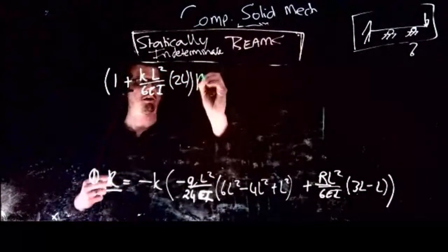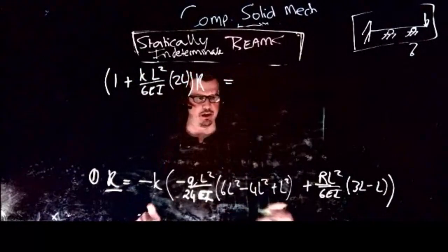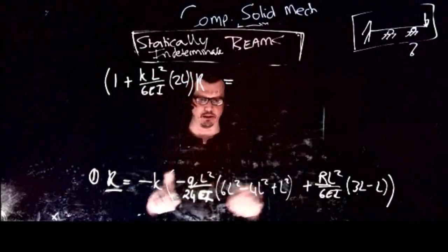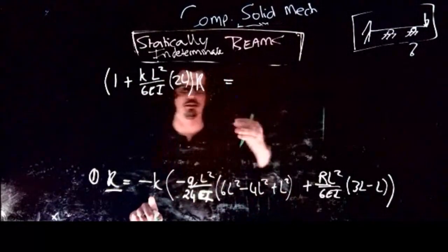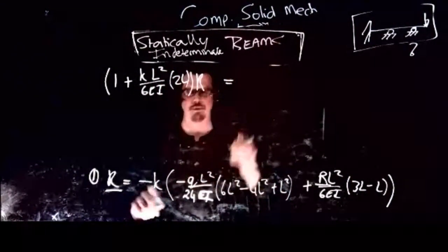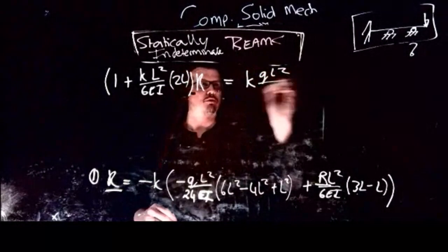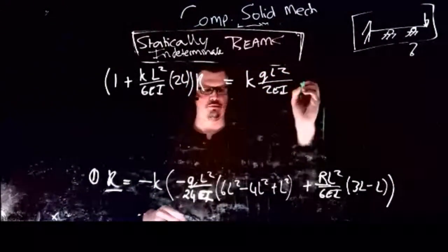And that gets multiplied by R. And that then essentially equals... everything here is known: K, Q, L, there's no unknown in here. So I can leave it on this side of the equation. The negative multiplied by then will become a positive: K, Q, L squared over 24EI.